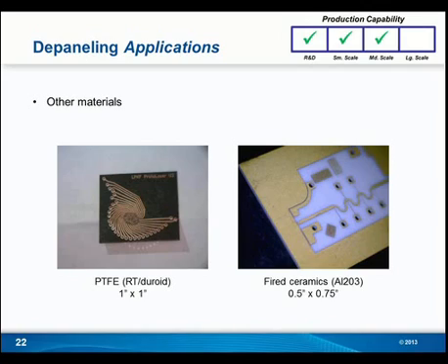Yeah, we use a lot of small scrap pieces for the research and development side, and the vacuum table is always included on the prototyping machines. If there are unused areas because of a small section, you can actually block that and focus the energy on your smaller sections of material. That would correlate to production until you get to the point where you would need the fixture and run high volumes. So, absolutely.